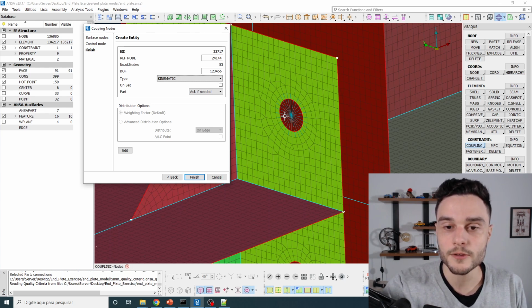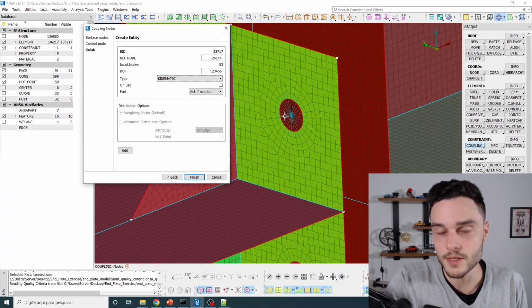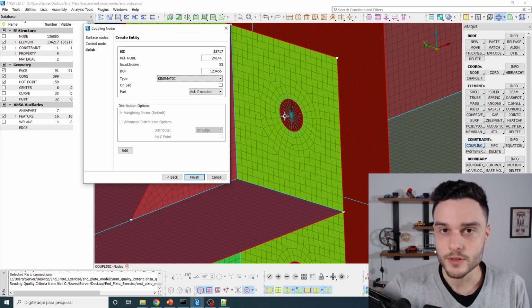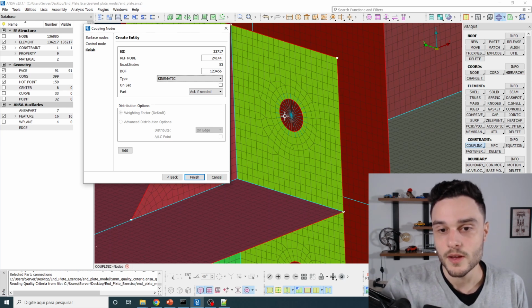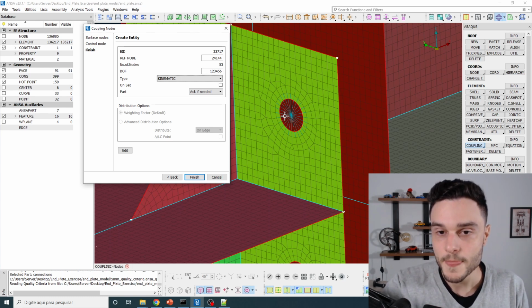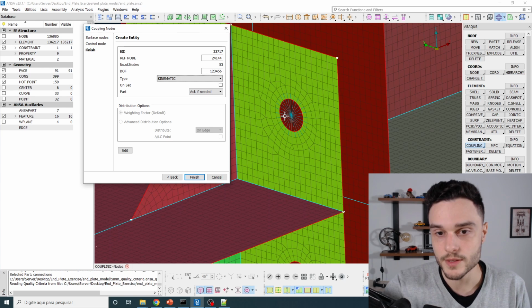And in this file, I had that, well, you should create the bolted connections using coupling, beam coupling, and the coupling should be kinematic or distributing, etc. So I would have all the orientations because they have tested this modeling strategy before, and they know that this works. And then if I use this modeling strategy, then my model is already validated. Okay, so this is how it works.